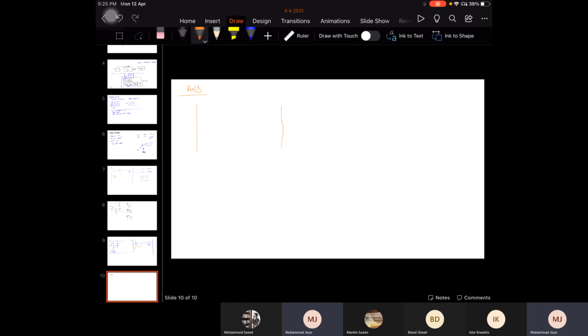If you have any two switches in series, it becomes an AND gate, right? So this is the definition of an AND gate. Let's say you have S1, S2 in series, and A1. Basically the operation here is an AND operation. How can you verify it? You can verify it like this. This is your S1, S2, and this is your A1.